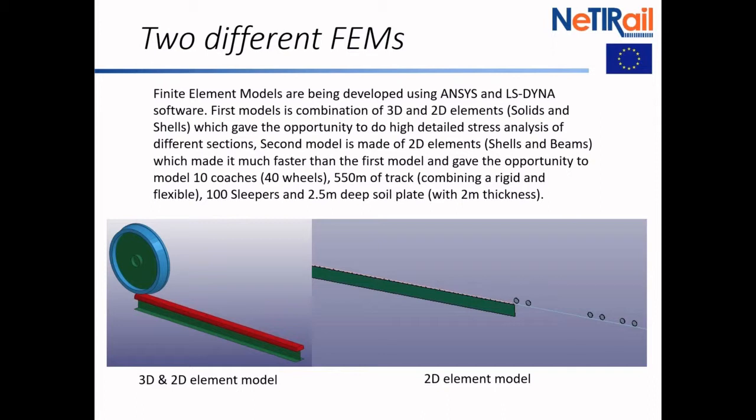During setting up the project, they had an idea about varying the mass of sleepers. And was there a way that by varying the mass of sleepers on the approach to a transition zone, you could reduce dynamic loads in the same way that we currently do with earthworks, varying the stiffness of the earthwork support.